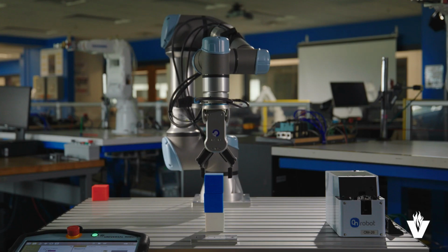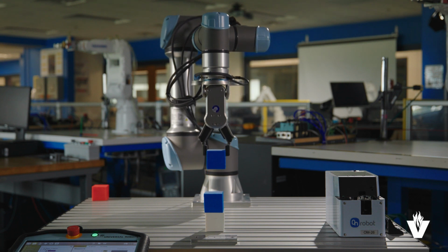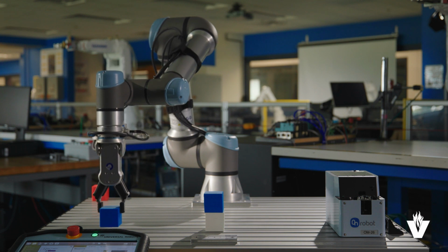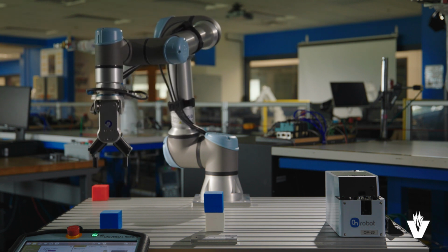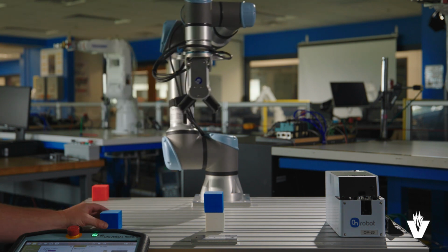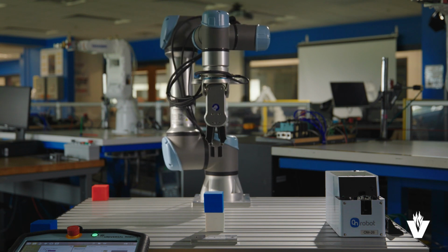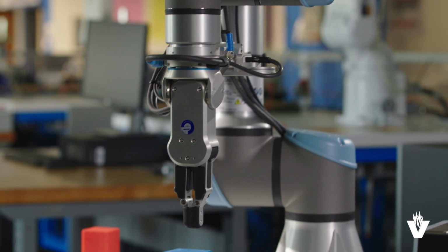After the part is gripped, we can tell the robot to move back to the approach waypoint and then to the set waypoint to set the block down. To repeat the unstack routine, return the robot to the approach position and it will repeat the first direction command until tool contact is made and repeat the process over.